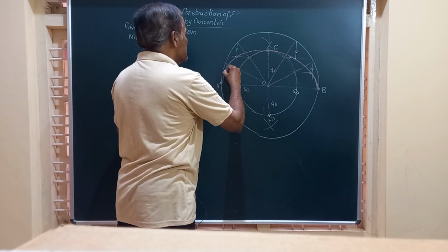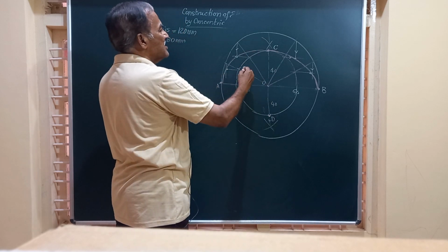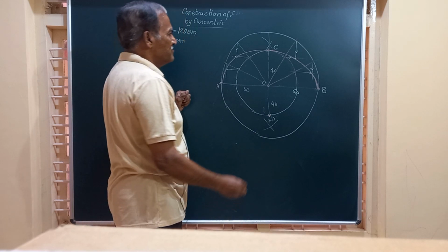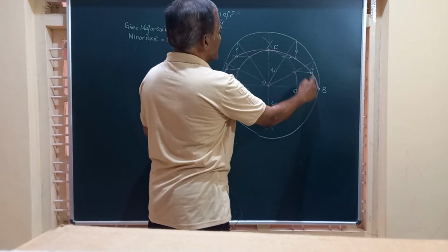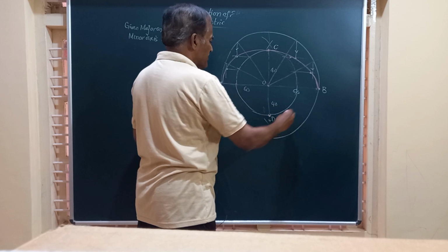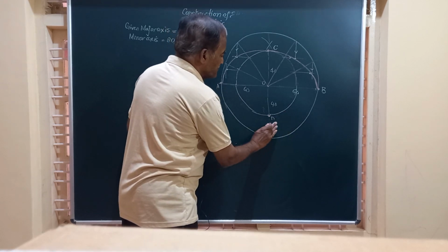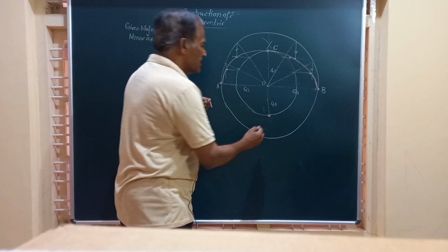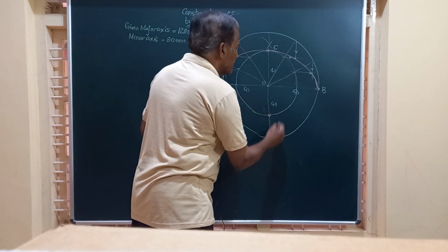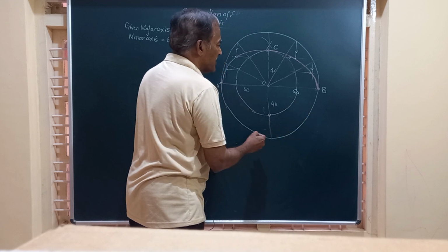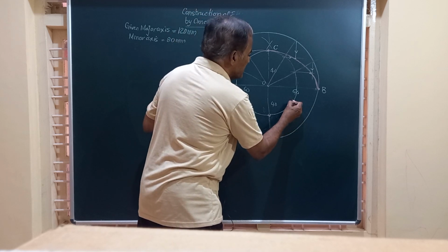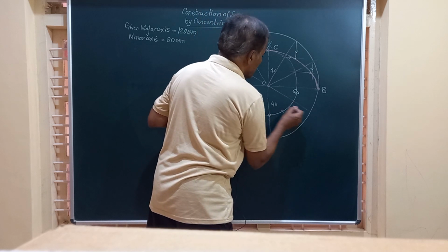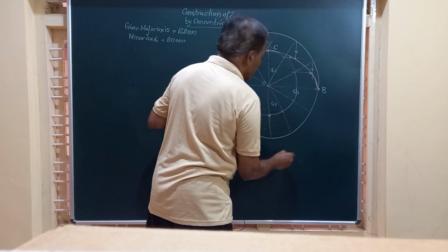Friends, remember, this curve is symmetrical both about the vertical axis and about the horizontal axis. And whatever the figure you get here, you got here, you are going to get on the bottom side also. Now friends, what I do, just see, you repeat the procedure. Now friends, if I am taking up this 90 degree, this quadrant, let us divide that quadrant into 3 equal parts, join that and extend that point.